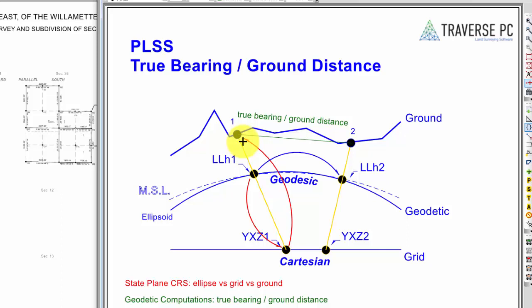Okay. Then I'm going to do geodetic computations, and this is the part that's a little bit different with the PLSS because this is a true geodetic survey. You might have a coordinate kind of survey where you're just doing planar coordinates at ground versus planar coordinates at your projected grid. That's fine too. It's all determined by the distance and direction type that you pick. Everything else works the same.